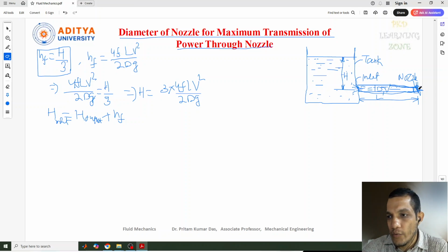So the liquid which comes out from this nozzle comes out only in terms of kinetic energy, that means in terms of high velocity, because the pressure energy is also converted to kinetic energy at this nozzle part. At the outlet of this nozzle we get the kinetic head.